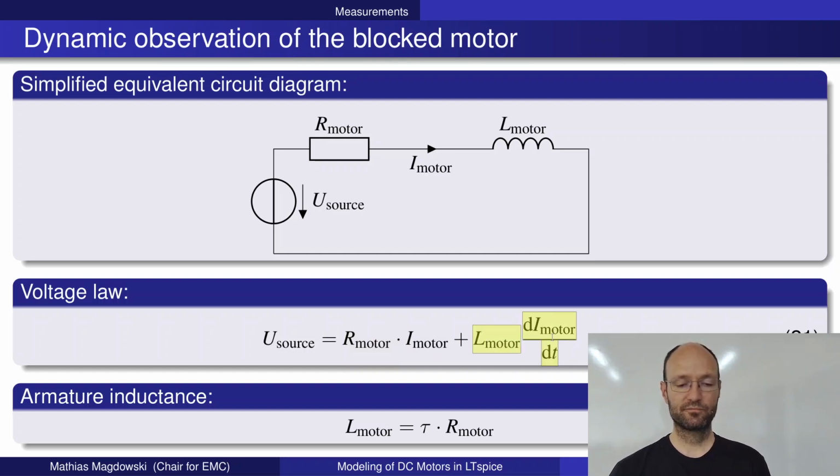And then this is your basic differential equation, a first order linear inhomogeneous differential equation, the simplest kind of differential equation that you can solve in mathematics. It would be even simpler if the source voltage were 0, then it would be the homogeneous one. The solution of this is this increasing exponential function.